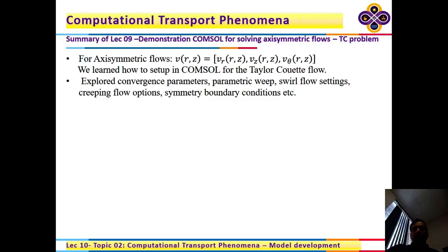Yeah. Okay, so it's a fairly straightforward thing to set up because we have seen it in class, but I wanted you to be precise because I was just throwing numbers of 1, 1, 1 for everything. But I want you to go after the transition from a one-dimensional flow to two-dimensional flow. And I also want you to look at what would happen if I have a finite wall at the top and the bottom instead of a symmetry boundary condition. Then what do you observe? Make comments on that. I won't tell you what you should find, but you will find the solution for that case.